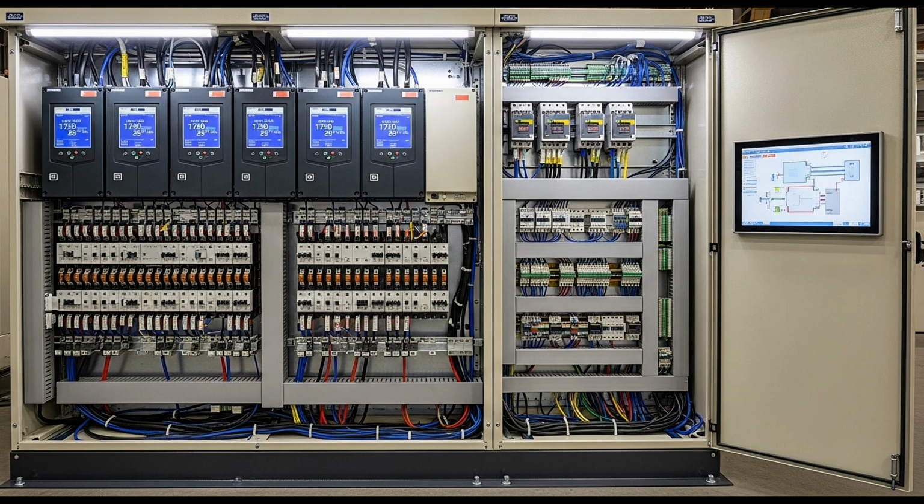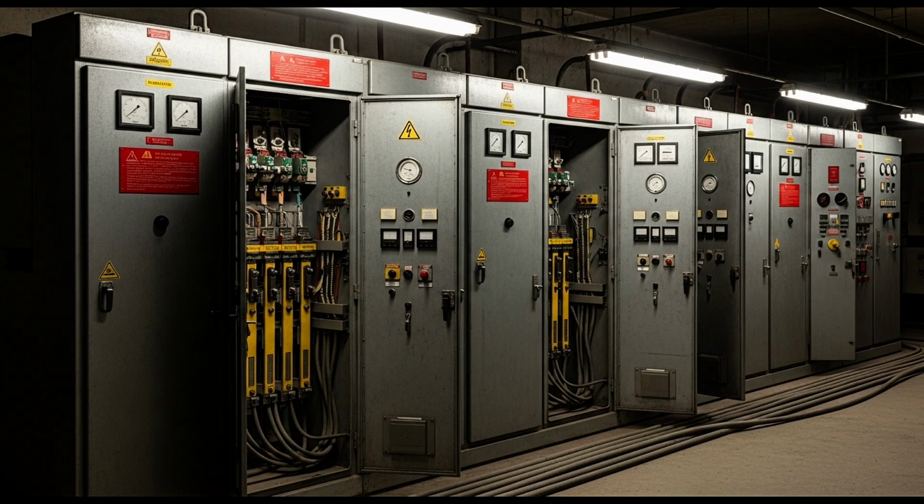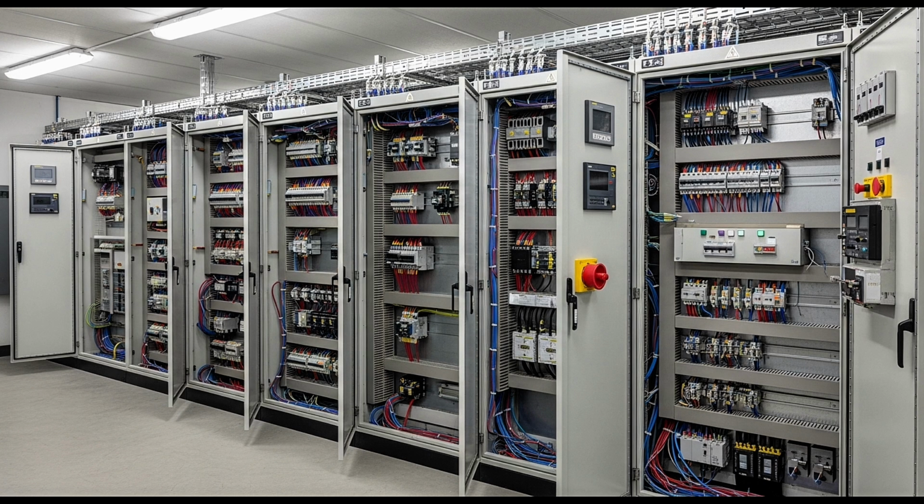grounding electrode system. This grounding electrode system might include metal water pipes, ground rods driven into the earth, or concrete-encased electrodes. Its purpose is to maintain the earth and the building's electrical system at the same potential, and to provide a path for lightning or fault currents to dissipate safely into the ground. When everything works correctly, you never notice this system.